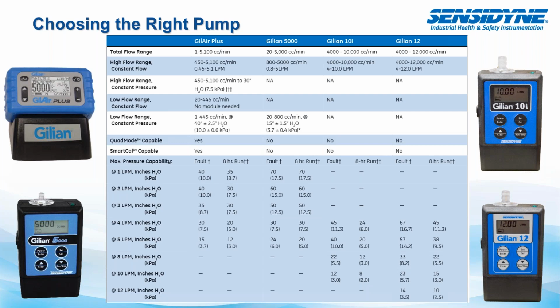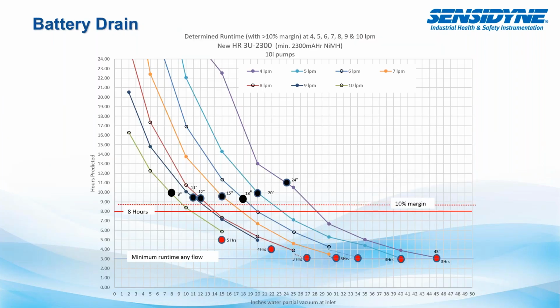to avoid those faults occurring during your sampling event. I brought in this particular illustration. Our engineers test all of our pumps at varying flow rates. So what this really is looking at is a correlation between runtime, back pressure, and predicted run hours.